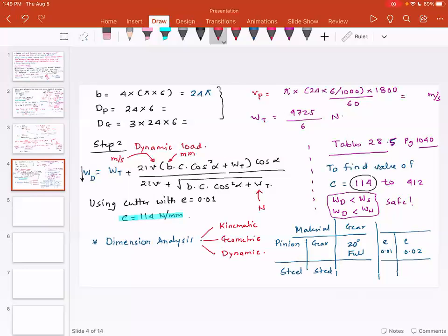So something like a design of experiment. How do you construct a small subset of samples? Rather than testing 1,000 gears of different sizes and shapes, I will make 3 gears which are representative sizes and shapes. And I will make sure from dimensional analysis that the gears I'm going to test have kinematic similarity, which, as a crude example, means the velocities are proportional.